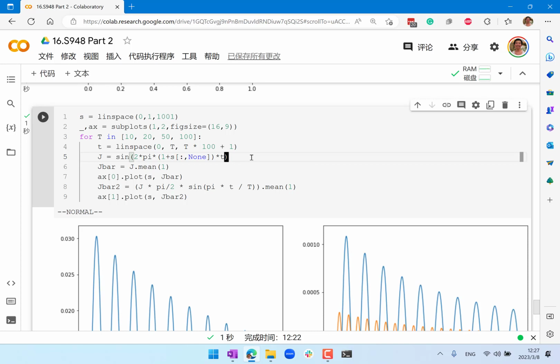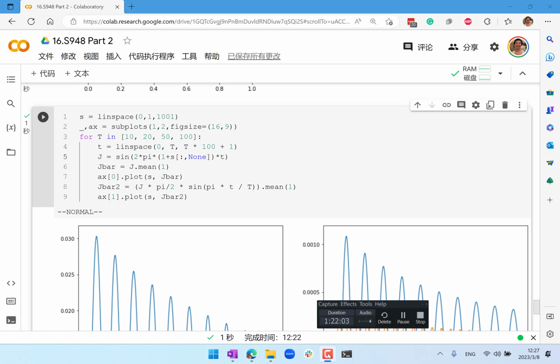And it also works when we want to average lift or drag coefficient for a not very long time. Yes. Let's say the idea is that after the limit cycle, we can capture the lift and drag coefficients and time average on that. But before that, it's a bit tricky because it's in transition mode. So if we use this windowing, will we get better results?